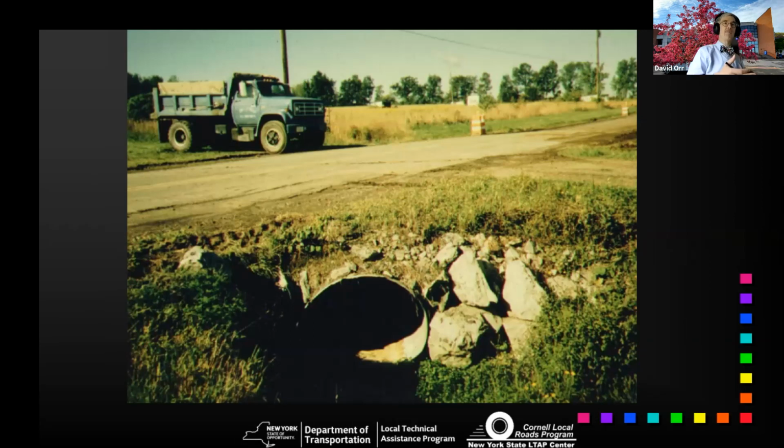Again, a 10-year-old pipe with rust probably didn't have something going on with bed load, or there was something going on with the pH of the soil. Pick the right material that's going to last, because you want it to be in the ground 35, 50 years at least. And all of the materials will work. You just might have to increase the gauge for metal pipe or coat it with asphalt or polymer or concrete.